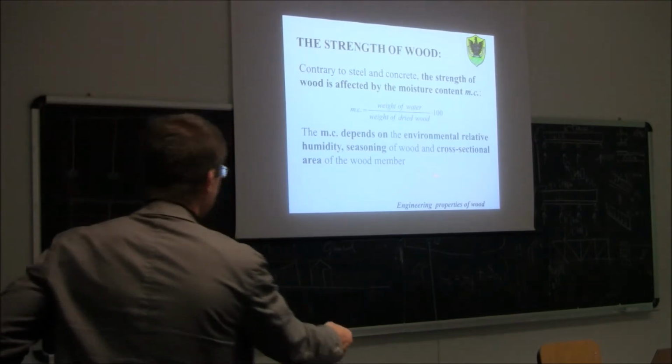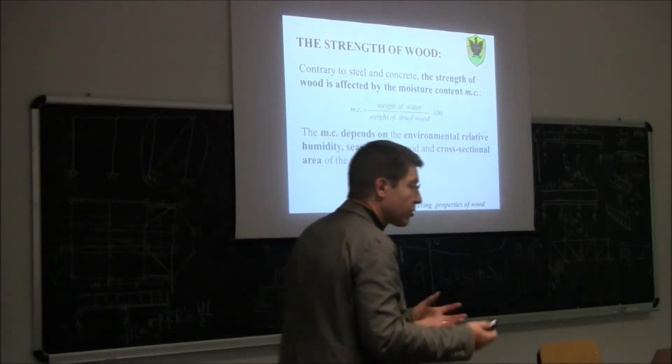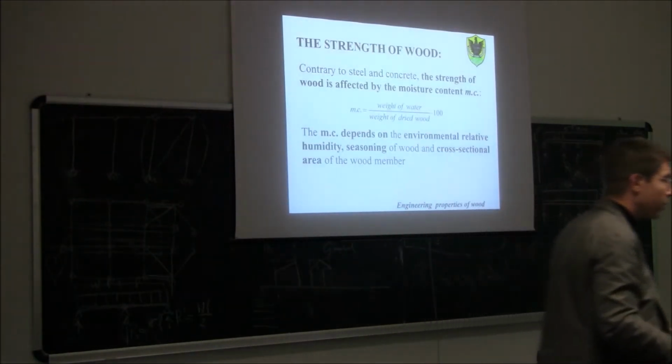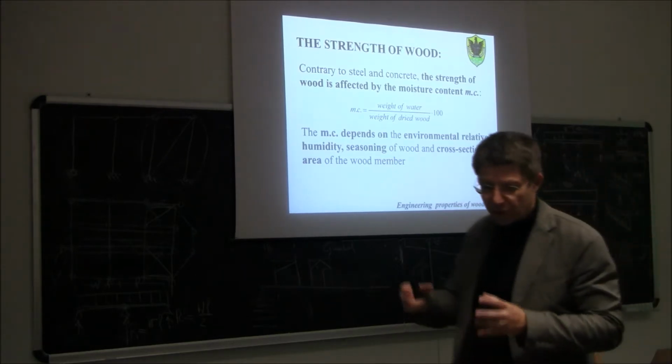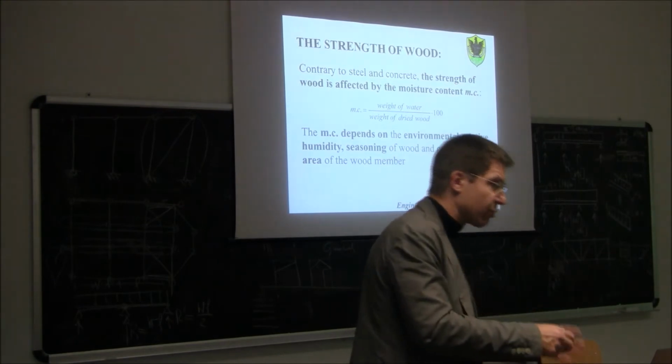Third thing, it depends on the cross-section of the wood member. If we have a very small piece of wood, in general the moisture content will change quickly because the cross-section is very small. Instead, if we have a very big cross-section, it will take, I would say, months before the moisture content of the cross-section is reduced to an acceptable level.